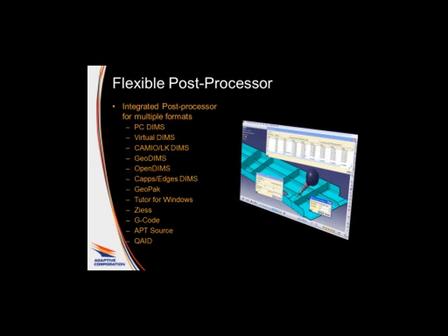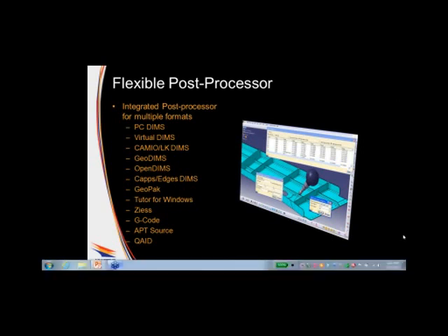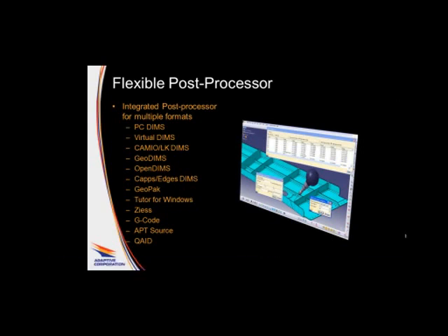Flexible post-processor. The concept of this product is you create your CMM program in native V5 and you post to probably one of the more popular softwares, some flavor of DMIS. And you can see on the screen here we support a lot of different DMIS flavors and some older CMM software. So the goal here is you do not have to change out your CMM controller. You do not have to change out your software. We create data that's ready to open and run in your environment.